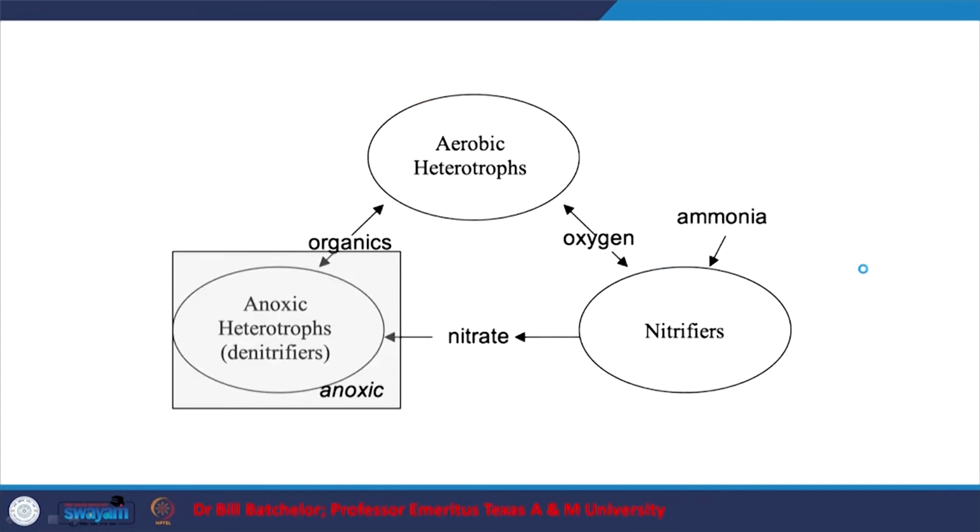So, the kinds of bacteria that we have: we know that NH4 plus oxygen goes to nitrite and nitrate. Here there is no organic compound; X, Y, Z and A are the stoichiometric coefficients. So there is no need for an organic compound here. I seem to have put in a typo, calling these heterotrophs, because you do not need any organic source of carbon. These are autotrophs, not heterotrophs, but they are aerobic because they need oxygen.